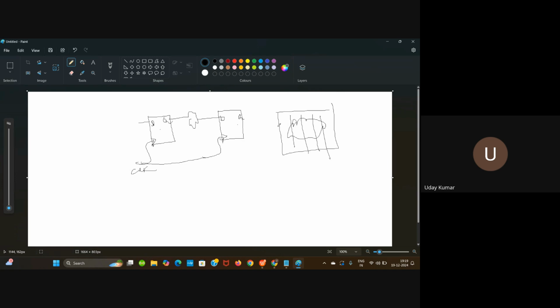Why do the pipeline? For more performance, for the parallelism, and so these pipeline stages will have flops. Anywhere in the design, you will be checking the timing between two consecutive flops. This flop will launch the data and this flop will capture the data. That's why this is called the launch flop and this is called the capture flop. So here comes the timing. This is STA. I'm telling you STA in a very brief manner because we have a shortage of time.